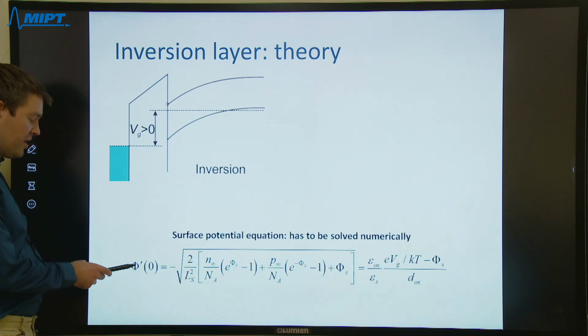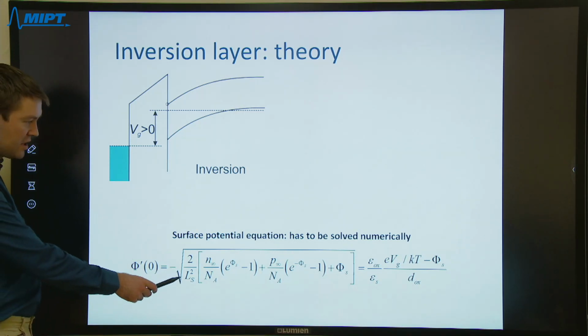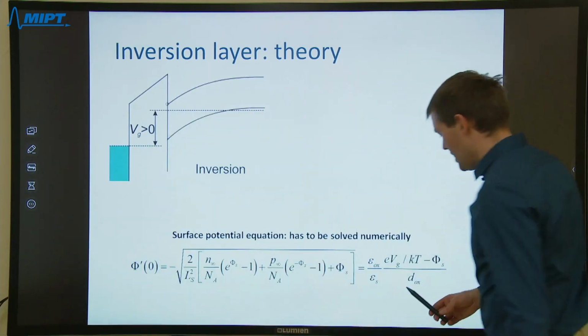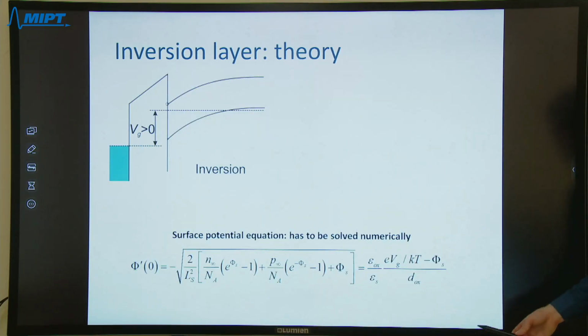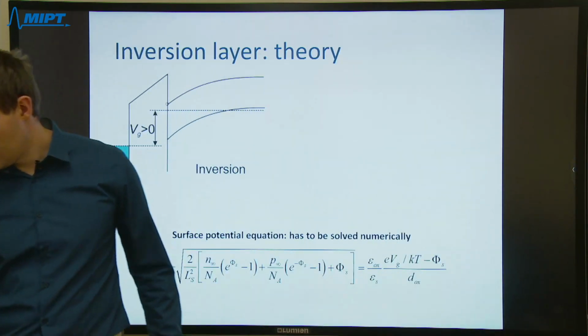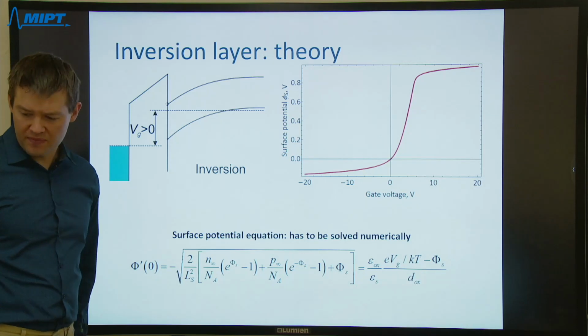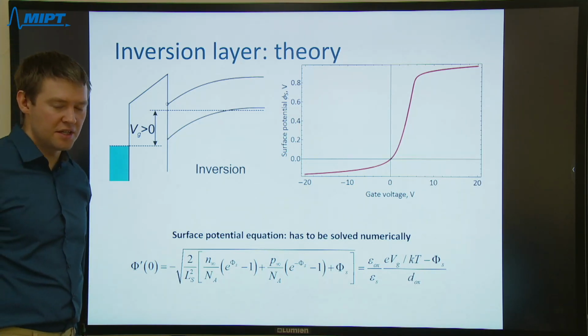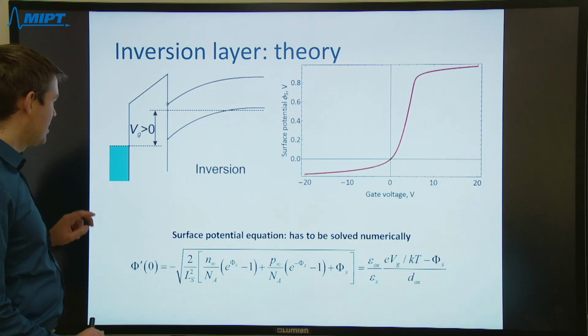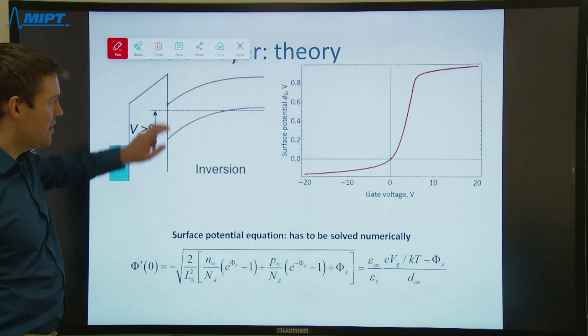The derivative of electric potential at the semiconductor side equals the ratio of the dielectric constants multiplied by the voltage dropped at the oxide side. This is a transcendental equation with respect to the electric potential at the surface. It has to be solved numerically, but its numerical solution is accomplished quite easily. I did it at home for some typical density of electrons in the semiconductors.